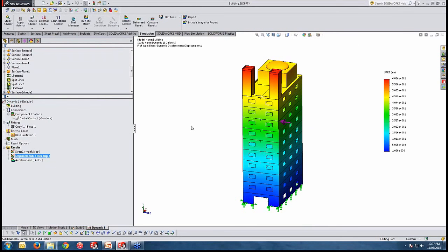Alright, so what is very important to understand is we are getting mostly positive values when we do the response spectrum analysis, and as we said, this is a statistical method of combining the peak response of the structure at different frequencies when we enter the graph spectra. That is again a very good estimation when we have huge models such as a building. Well, it might take a very long time to resolve with the nonlinear dynamic. But again, I'm emphasizing a more precise answer requires a lot of time to study.